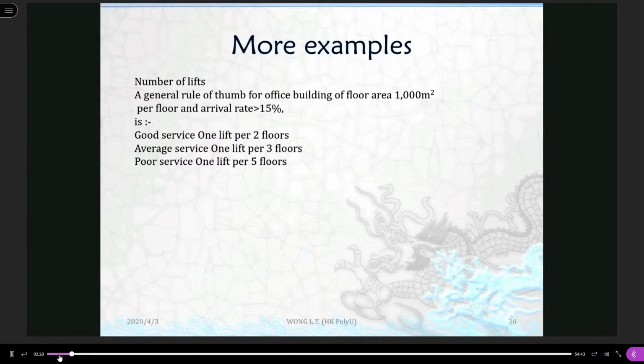point it helps is to cross-check our detailed cooling load calculations and detailed design against those of typical buildings, typical cases. See if our case is also typical, so that our calculation should fall within the reasonable range.